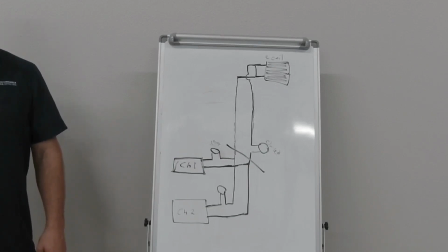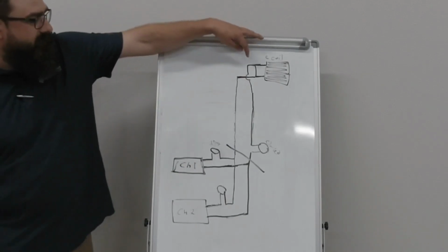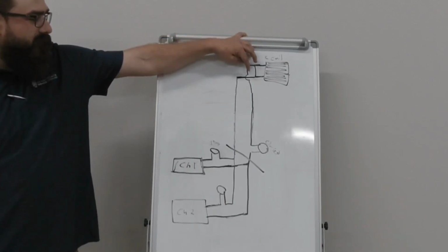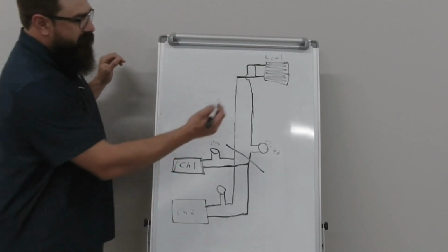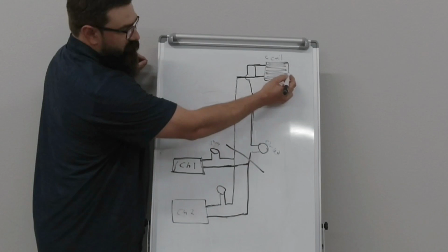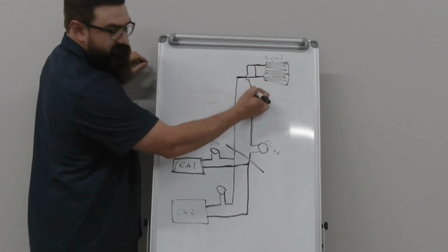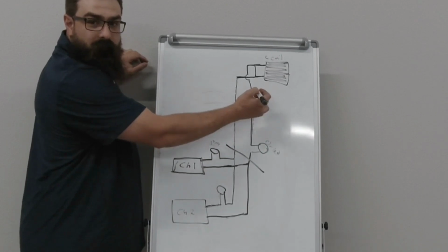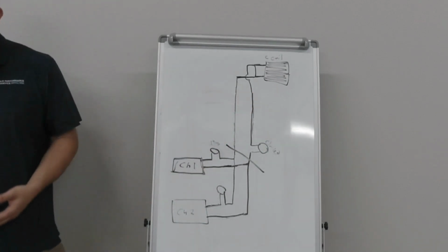And you don't cavitate. So on the bottom of the unit, you would have a three-way valve. And what it can do is it can vary the amount of water that goes through that, but whatever doesn't go through the coil returns back into the system. That way we maintain constant flow through the pumps.